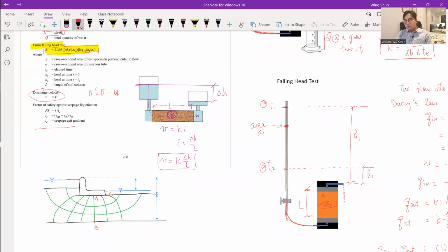And if we lose all the effective stress of the soil, then there's no more strength. And at that time, the sand could behave like a liquid. So it's quite terrible. That's why, when you have a loose sand deposit, because of an earthquake or other dynamic loading like blasting, or maybe even static loading that allows you to generate excess pore pressure, we always need to keep an eye on it, because if the pore pressure is too high, then liquefaction can happen based on the effective stress concept.